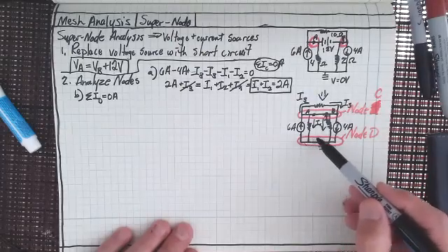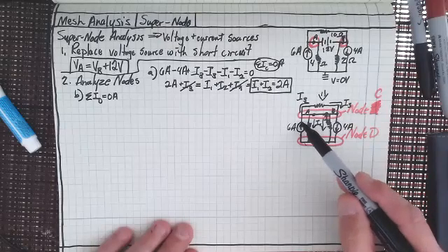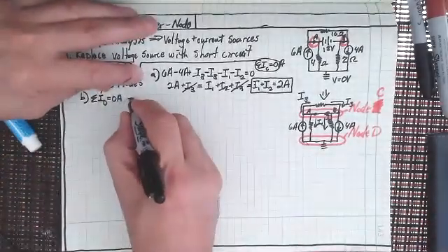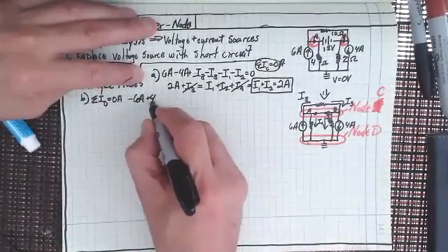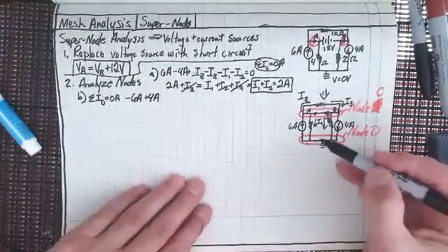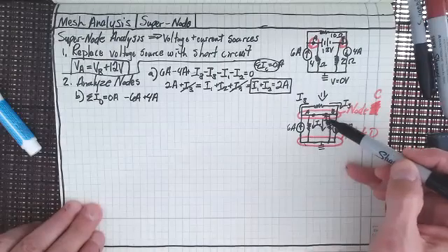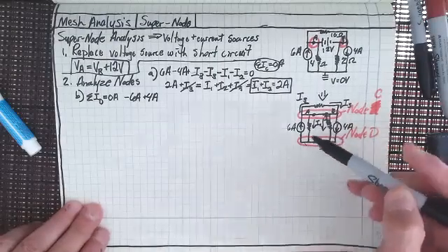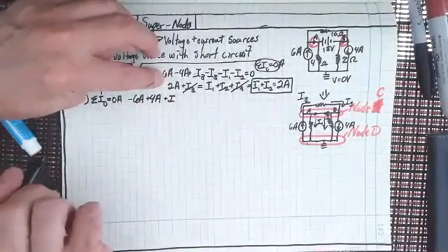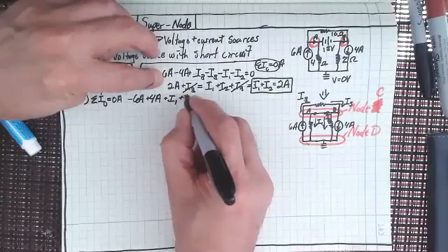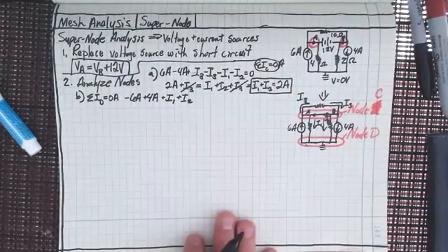But I have my currents here. So my current flowing in or out is going to be 6 amps. Let's do that. So minus 6 amps. You know, I've got 4 amps that are flowing into that, right? And then I also have the current I1 and current I2 that are flowing into that node. So I'm going to say plus I1 plus I2, right? So